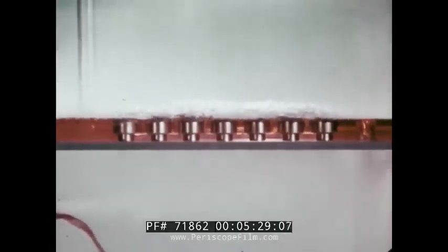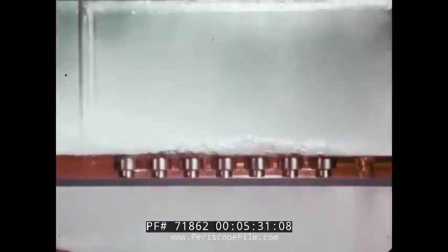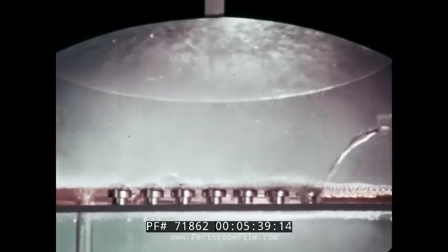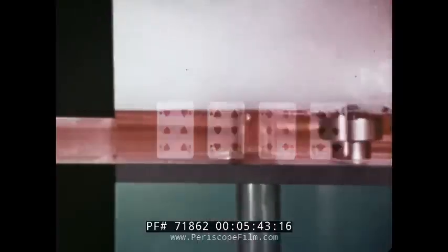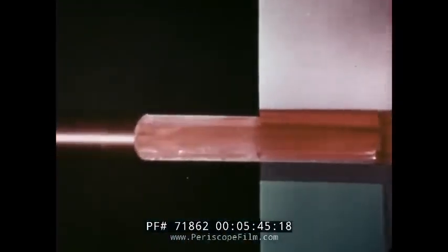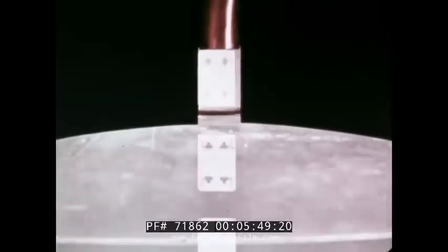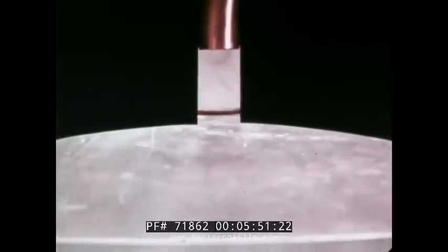The remaining vapors bubble through this liquid and rise to the next tray where they are cooled further, below the boiling range of the next heaviest fraction. This condenses, and it too is drawn off. The vapor that's left is drawn off the top of the column and condensed.